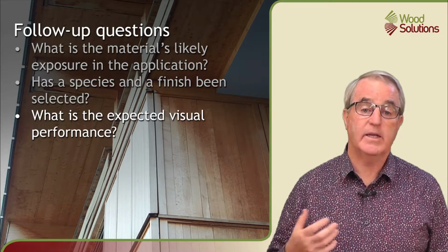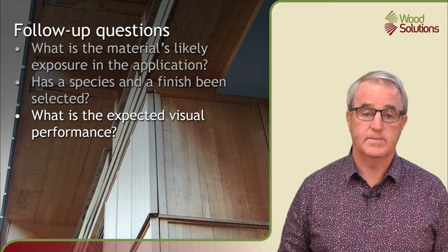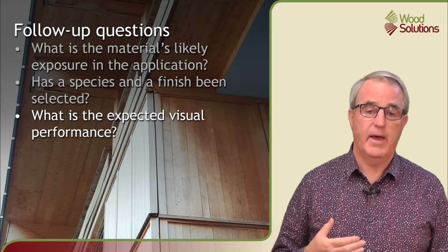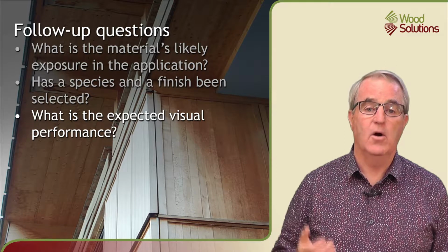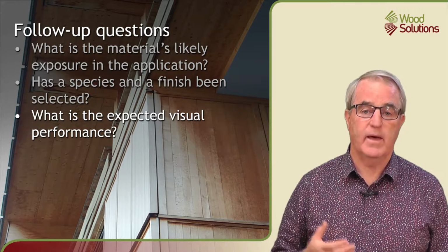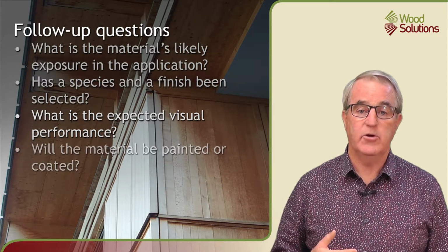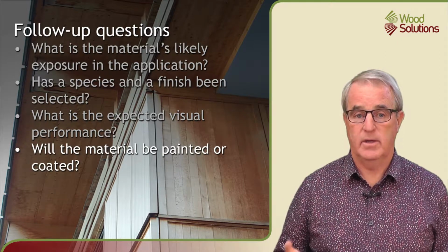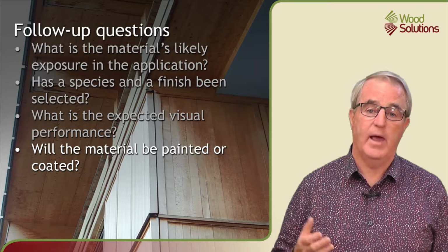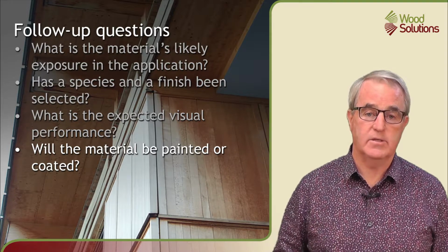Next, what is the expectation for visual performance? Unless protected by a paint or a well-maintained coating, all timber is likely to weather and go grey if it's used outside. Is the material to be painted or coated? This is important as it will add to the timber's protection and its service life.